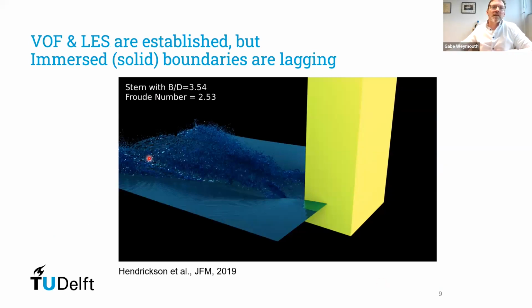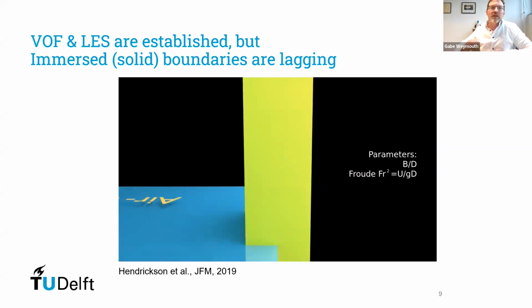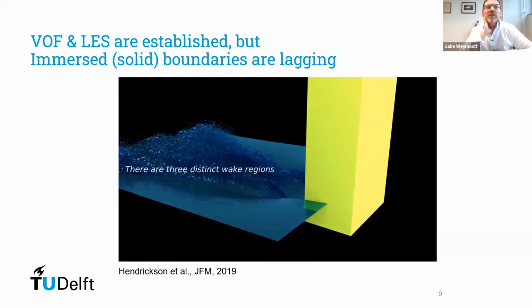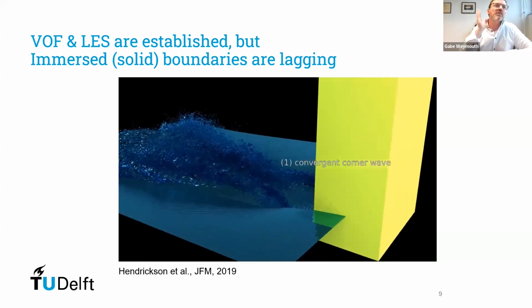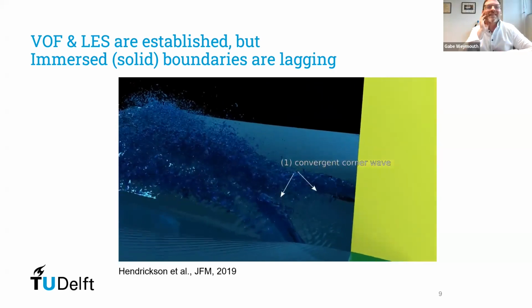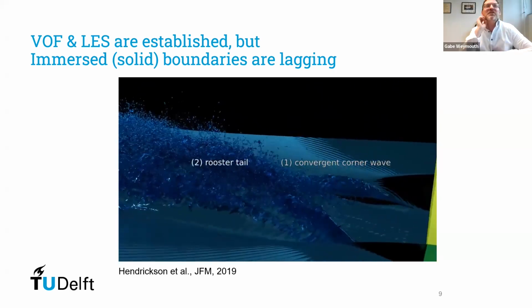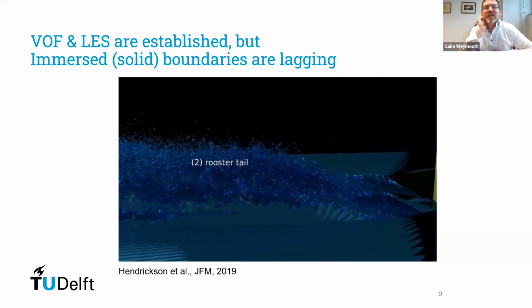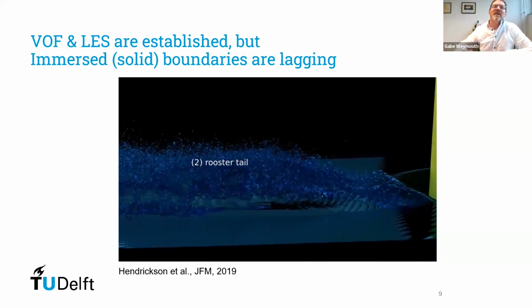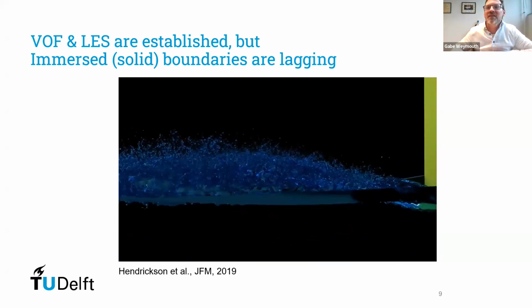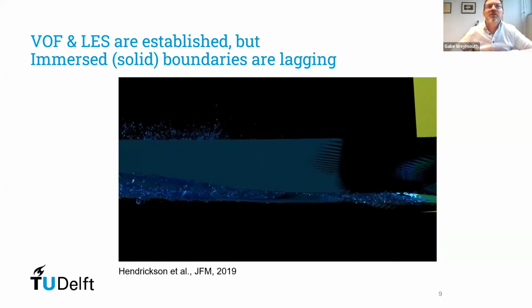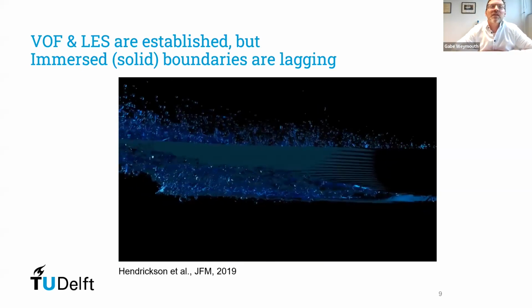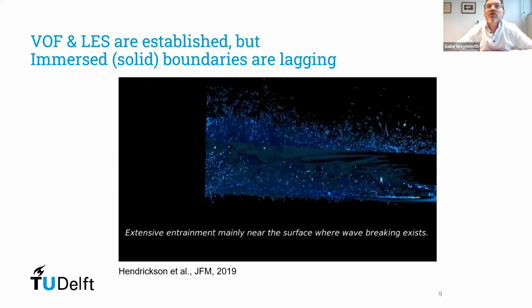So I think Cartesian grids have kind of been the agreed upon solution for difficult two-phase flow simulations for quite some time. The volume of fluid method is a very good way to do two-phase flow simulations. But the big yellow box there has to be done too. So this is the flow past a ship kind of model, and we're looking at the rooster tail behind it. And nobody bats an eye about trying to use Cartesian grids to deal with these very complicated structures because there's just no other way to do it.